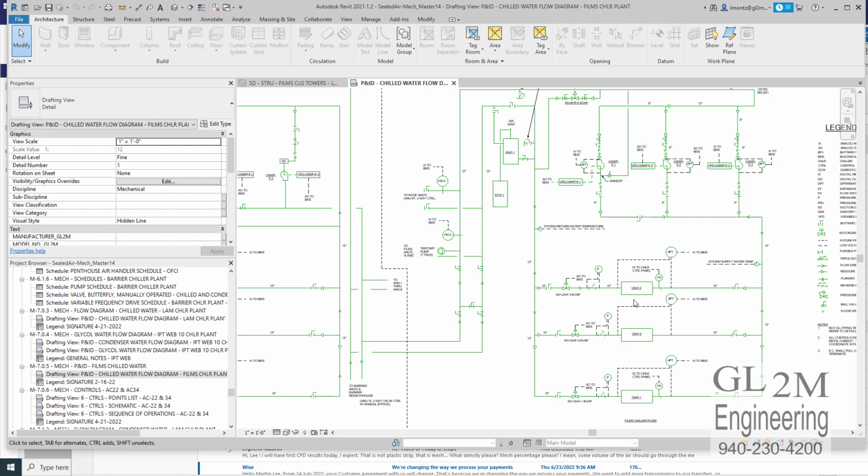Centrifugal chillers have some interesting operational things about them. You can spec a 700-ton chiller and get 800 tons out of it. In fact, we spec'd a 750-ton chiller for this same client, and then we tweaked the chiller selection and we were able to get 837 tons out of it. And we didn't have to pay any more for that, except we had to pay for bigger pumps to flow water through the condenser. We didn't have to pay for a bigger chiller. And pumps are typically inexpensive. It wasn't a super high cost to get an extra 88 tons out of that chiller. And for this particular facility, they'll take all the capacity they can get.